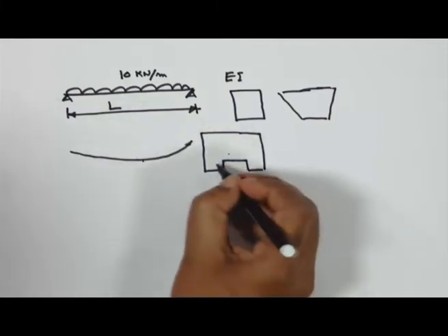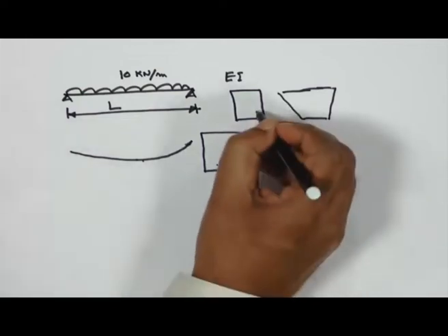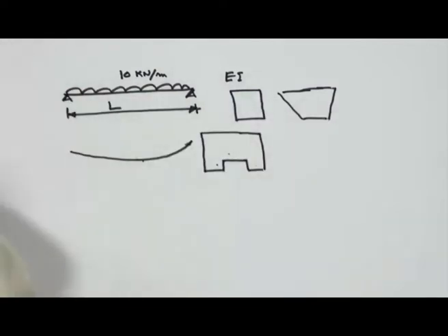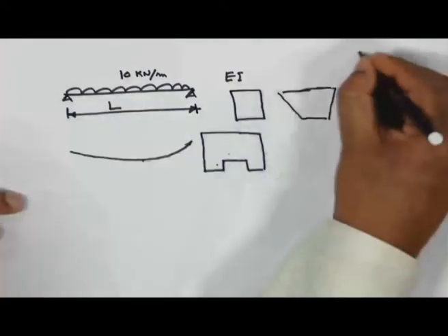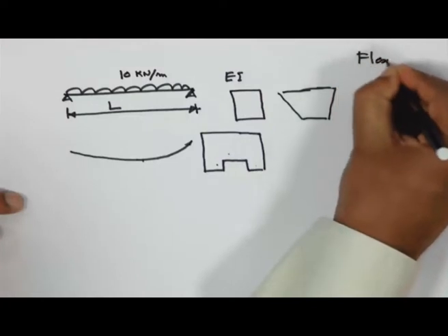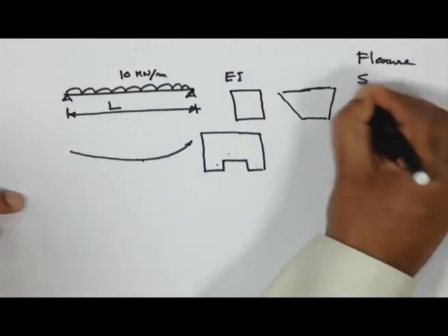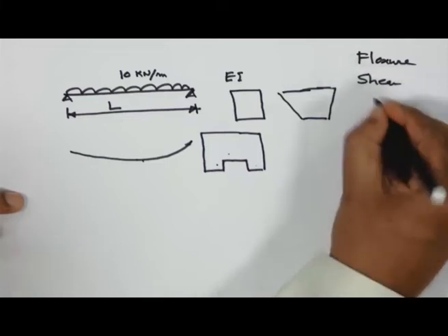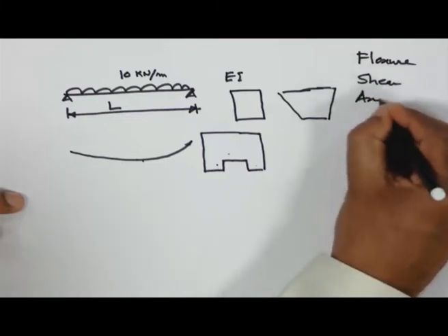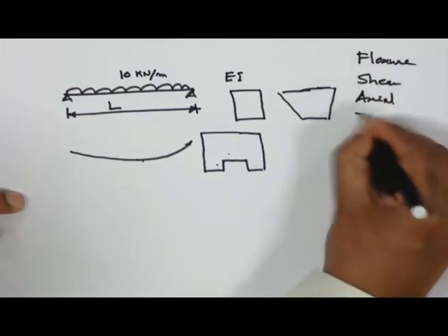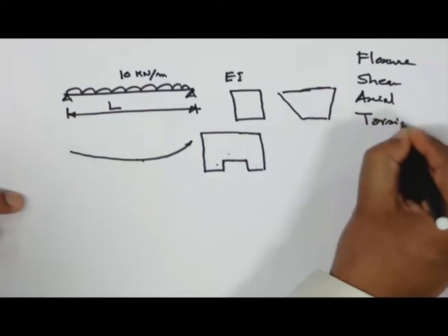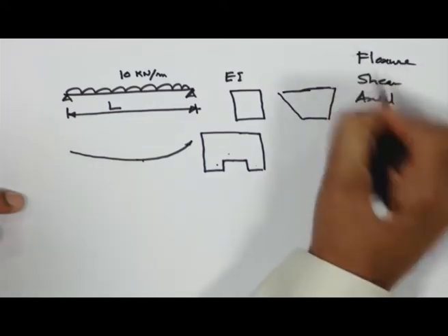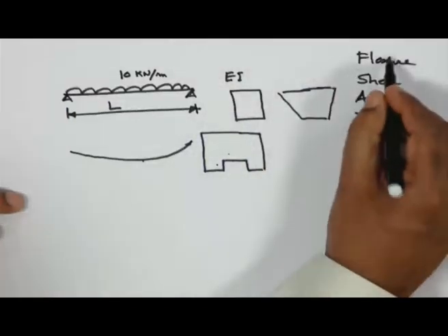So we shall get the value divided by BD, where B is the width of the beam and D is the effective depth. So we shall find that out. What is this? This is what we have to provide: stirrups in this fashion also. Longitudinal bar we have already provided. So this is the bending one we have to calculate. In a similar fashion we can also consider providing the reinforcement.